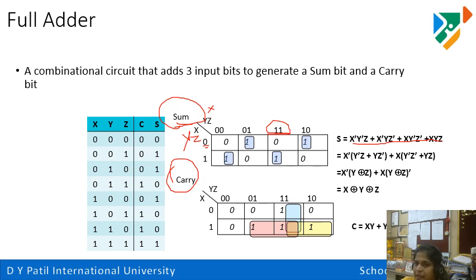After writing the K-map, if you are not able to pair it, then we try to simplify them with Boolean algebra. So pairing them accordingly, splitting it, making use of the associative law, we come across that we get x XOR y XOR z. This is how we get it, because we take out the common terms here.